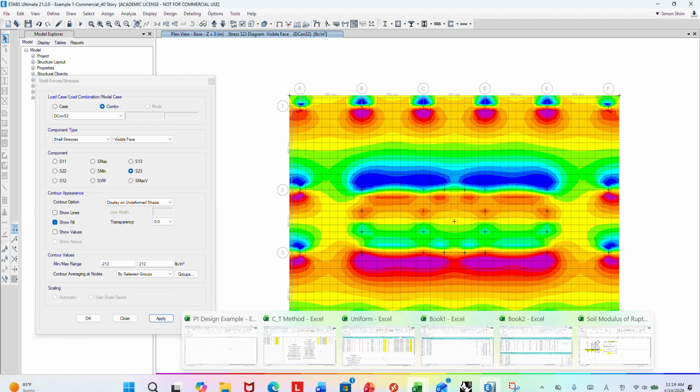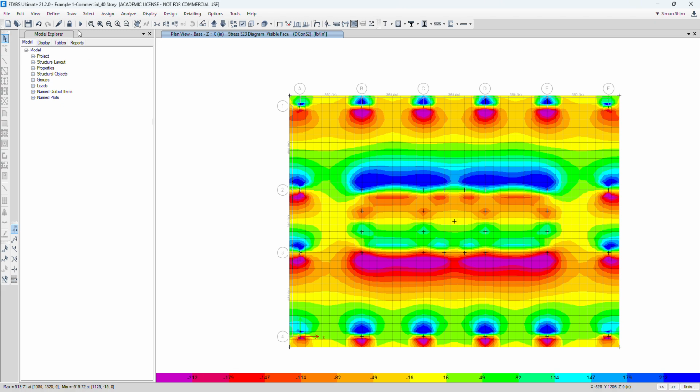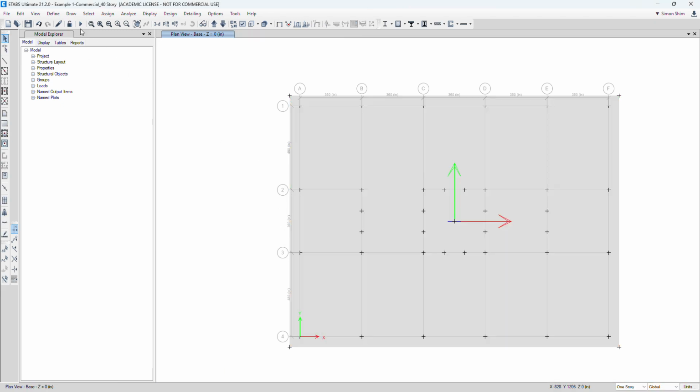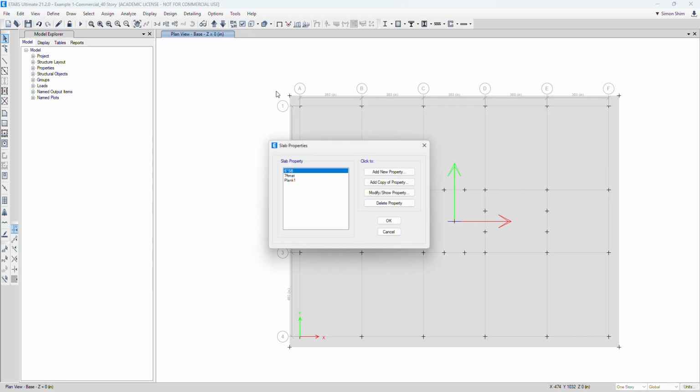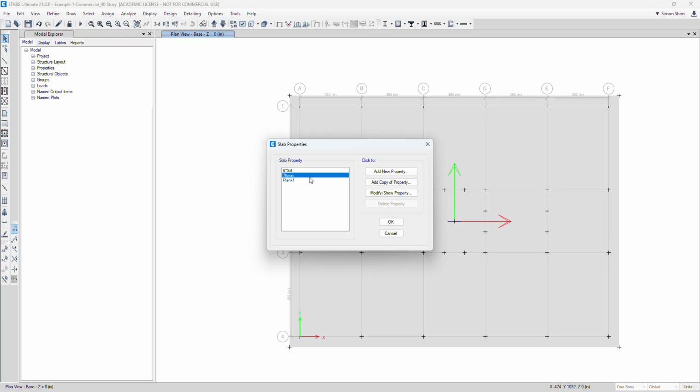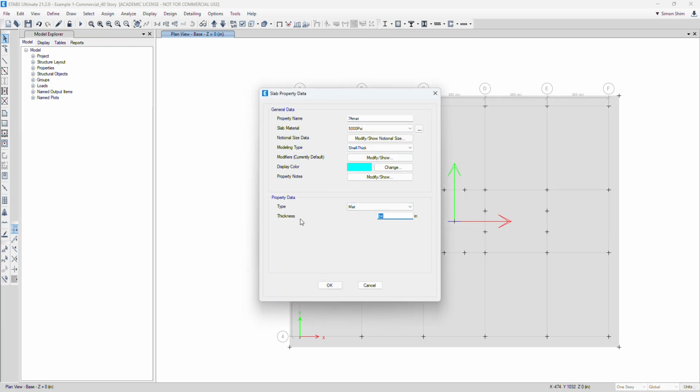So we need to think about it then, okay? There are two choices, mat or beam. If you have excessive shear stress, what do you do? Increase the member size. Or we have to add shear reinforcement, right? It's identical. The approach is identical. It's only two way. So this mat is experiencing significant shear. So I think maybe let me size up one more time. Okay, 7 to, let's say, how about 8 feet?